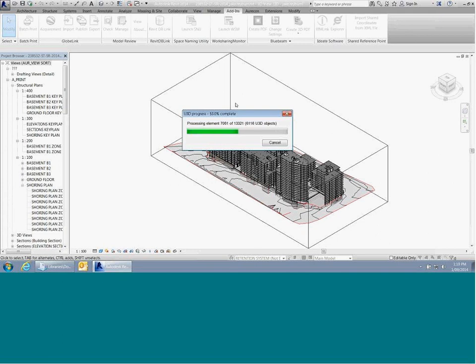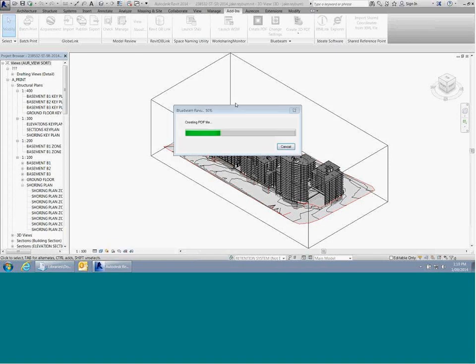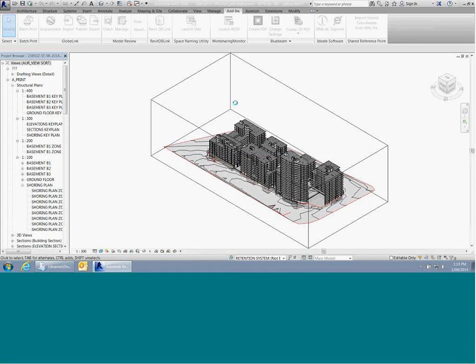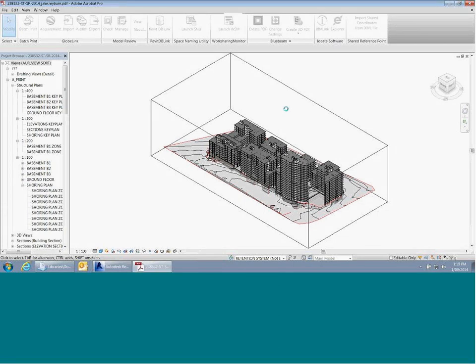So how many linked models have you got in there? There's 7 buildings, isn't it? And the basement, because this is the site retention model, plus the topography? Yeah, that's in this model. Or 7 or 8. 8. Topography and stuff comes through as well. It's a bit odd with building pads sometimes. Not sure why, but you can always hide them in your view. You can't delete them from the actual 3D PDF, but you can hide them and save your view so it doesn't show up.